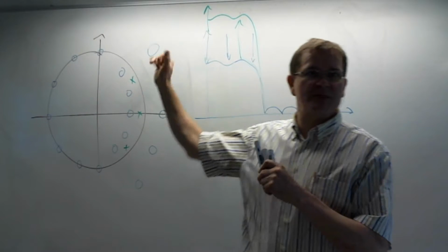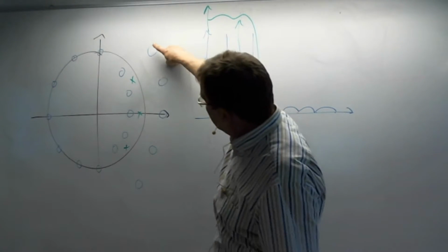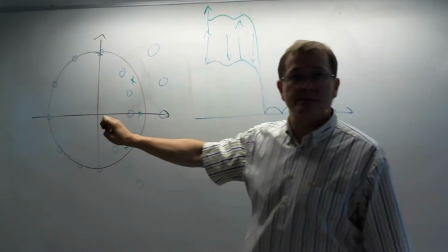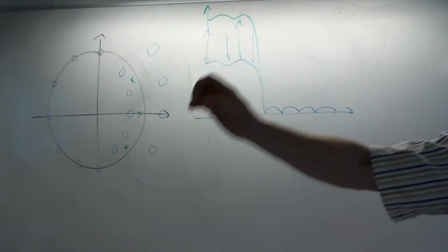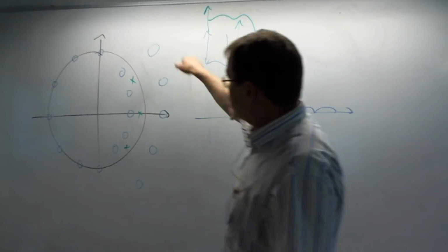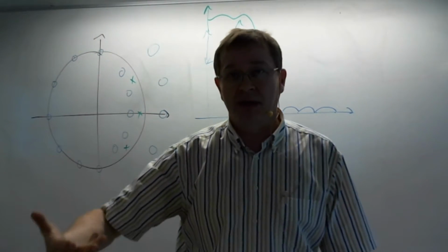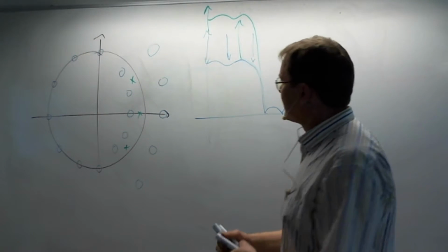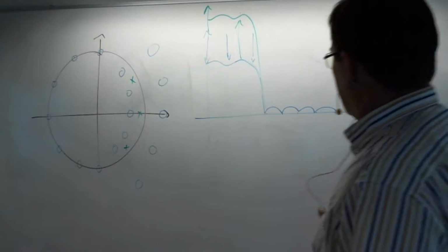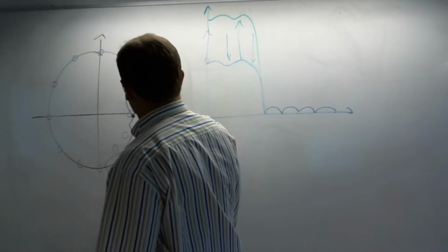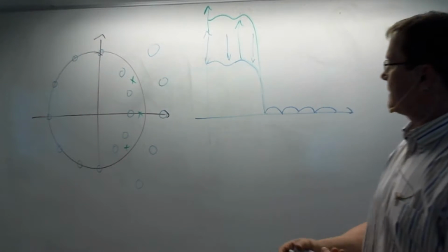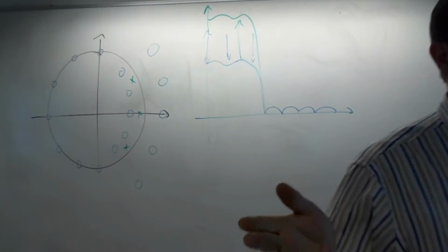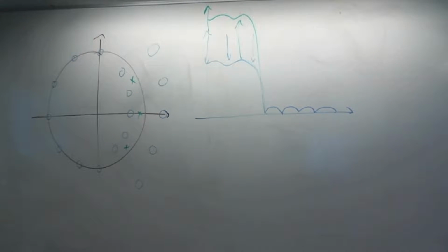It's quite obvious when you look at this, since every one of these requires one multiply accumulation. The number of zeros and poles is the same as the number of calculations plus one. So, better efficacy with fewer calculations. That's the IIR, why we are using IIR filters.